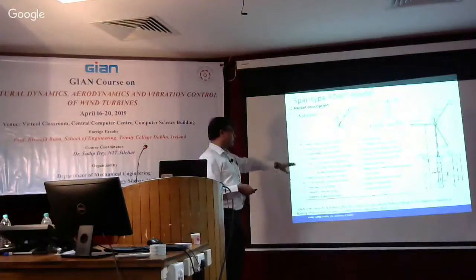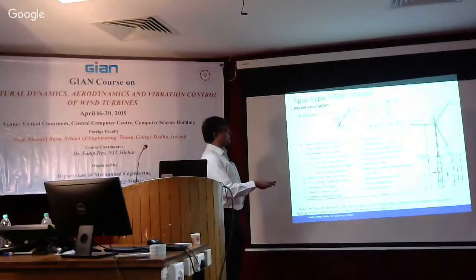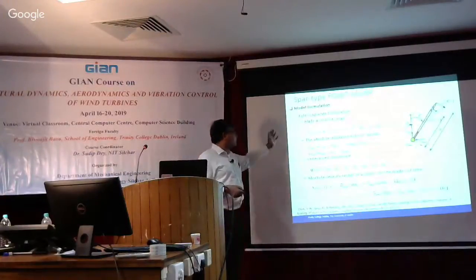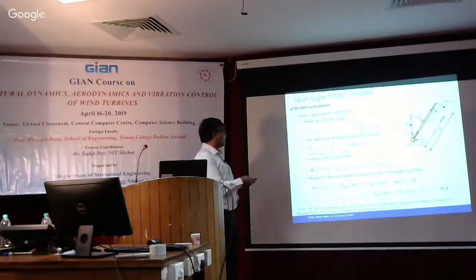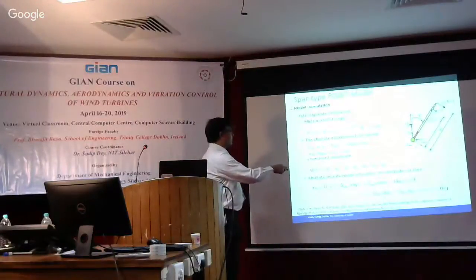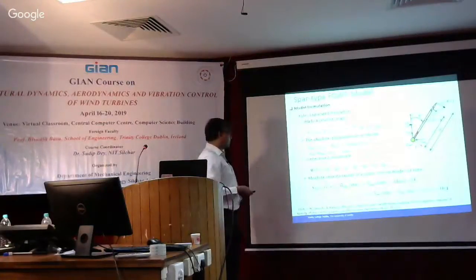So some more definitions here which you can find in this paper. And so this is what we define as sway. We're considering the sway motion, and the heave is in the vertical direction. And again, the same azimuthal position, Euler-Lagrange equation, displacements as we have considered previously. Now, obviously, because the nacelle is not just laterally moving, but there is also a tilt because of the tilting of the platform, that is accounted for in this additional term here. That's what is coming from the offshore, which was not there for the onshore wind turbine.